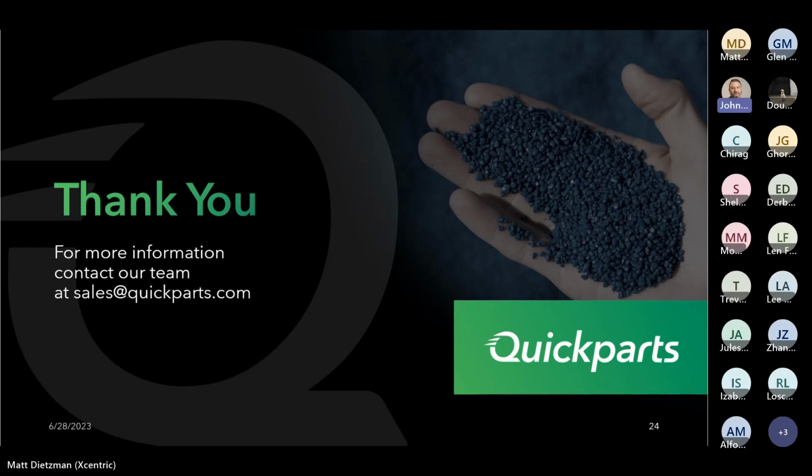Okay. Next, for hand mixing of colorants, how do you go about determining the ratio of colorant to resin? So our color house will send the version, the native material. So maybe it's a Lustran 348. We'll send that material to them. They'll develop the master batch for that colorant or for the Pantone that they're doing, and they'll actually determine the letdown ratio. And that's what we'll use moving forward with that colorant.